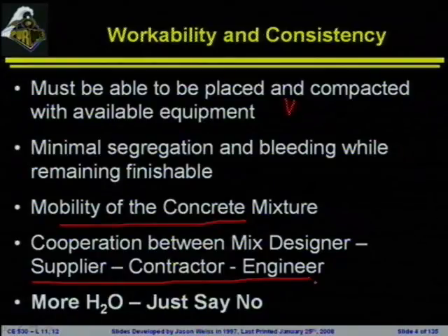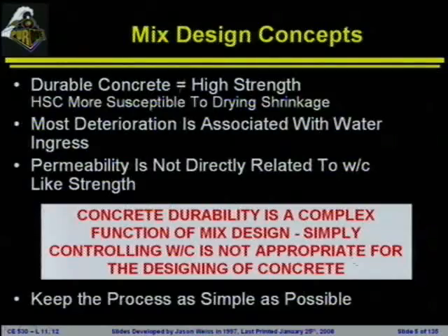The one rule that you should walk out, at least today, thinking, much like watered down drinks at the bar, just say no to H2O. All right? Water should not be added indiscriminately. And that's a phrase that comes from the National Ready Mix Concrete Association. The indiscriminate addition of water should not be tolerated. Translated into lingo that we all speak, don't add water. We will come back to this over and over again. There are issues with adding water. All right, we have to be willing to just say no.